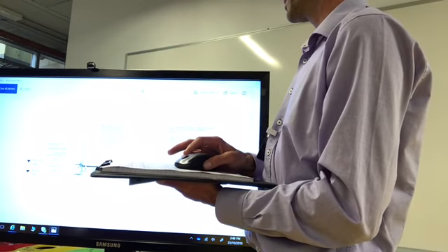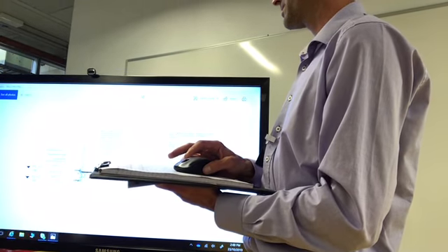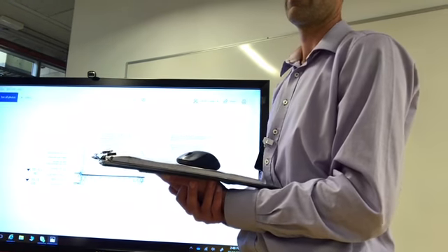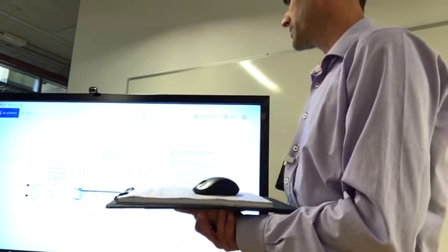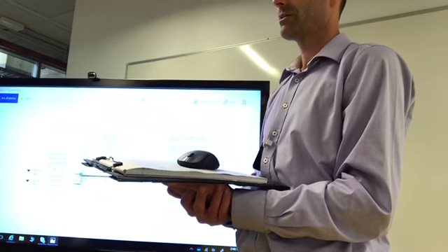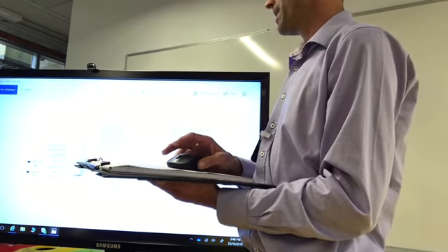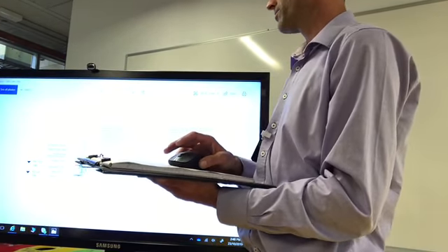Another thing that's going to be similar between both details is the fall. So you're going to have a fall of 1 in 100. Because we're dealing with very small balconies and they're at the rear of the building, I'm happy with water runoff to be going off the edge of balconies for your details.